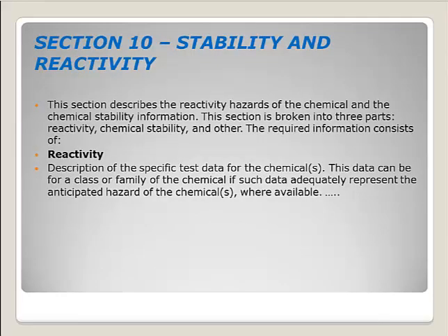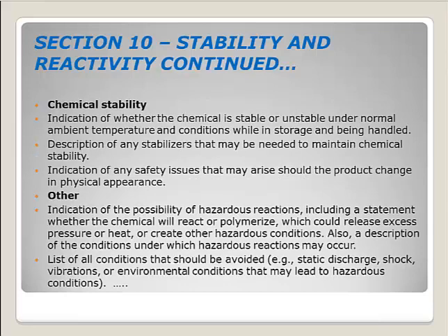Section 10 speaks of stability and reactivity. So reactivity, how is this product going to react with other items? What do we need to be aware of and concerned with? Chemical stability, how stable is the product? It tells you whether or not you need to be concerned if it is in normal conditions. Does this product need to be at a certain temperature? Anything that would cause the stability or some issue pertaining to that chemical would be discussed in that section.